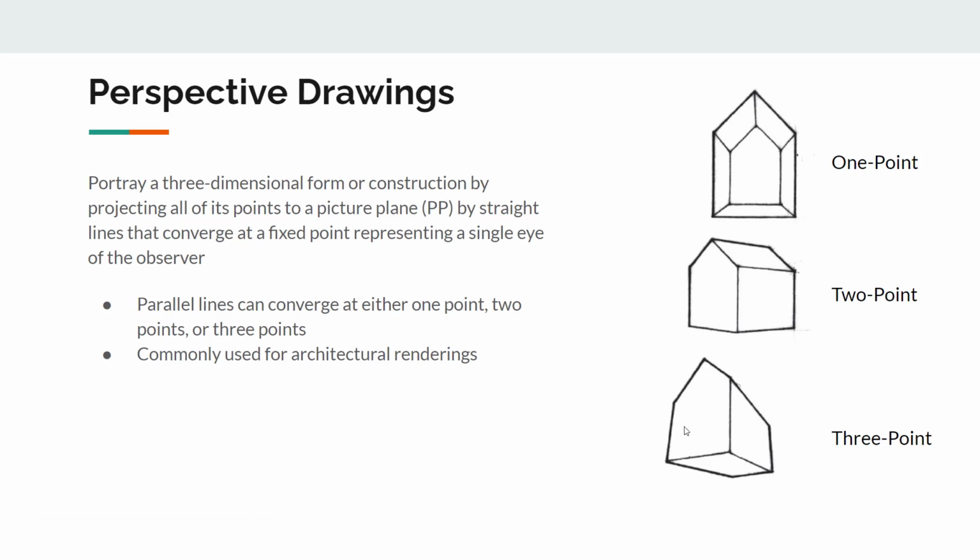Like when you see a photograph of a building, usually that's a 3-point perspective, because a 2-point perspective is actually a bit distorted to make all the verticals totally perfectly straight, as you can see here. We usually like to use 2-point when we do architectural drawings because it just makes the building design look better. But 3-point perspectives are usually what you'll encounter with an actual photograph, okay?